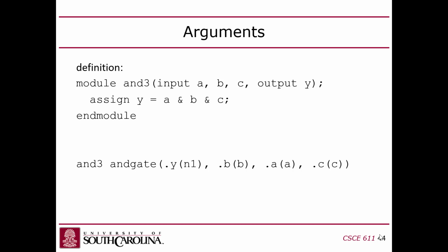But when you synthesize your design, it gets flattened. There's no hierarchy in real life. That's all just a concept, right? Ultimately when you synthesize it, it gets converted to a big rat's nest of wires and gates, wires and LUTs on the actual chip. So all of the naming and separating of things in a module kind of disappears when you synthesize it, but when you simulate it, you can see it. But even in simulation, you very rarely will even refer back to this name. So it doesn't really matter what you name anything, which is kind of funny, but you still have to give it a name. So AND3 AND gate has to be a unique name.